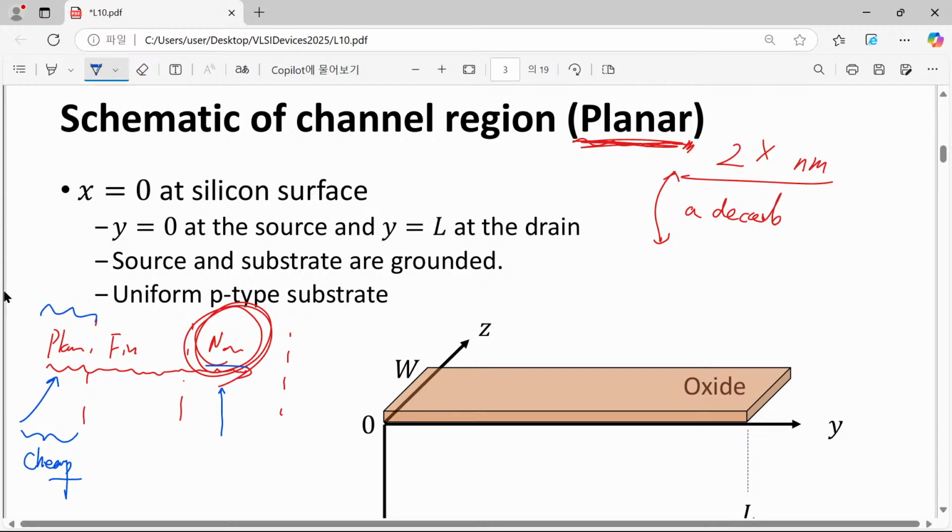But there are many other uses. For example, if we are just turning a light on and off, can we use FinFET or nanosheet technology? Actually, that doesn't make sense. So there are still a lot of planar MOSFETs available. And another case is especially important: if we go to some specialty technology and specialty applications, even FinFET or nanosheet technology suffers from certain technical difficulties.